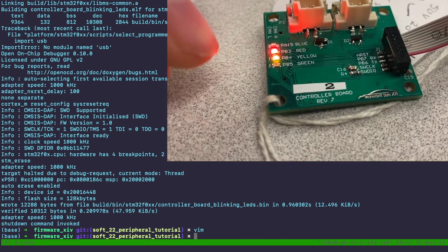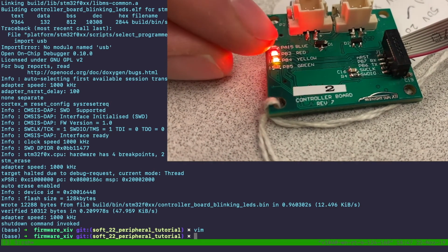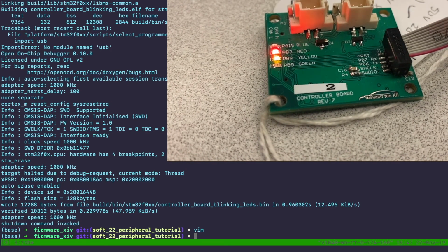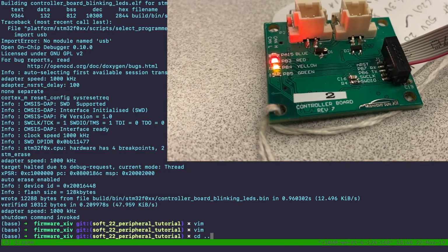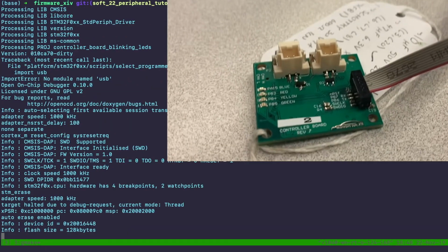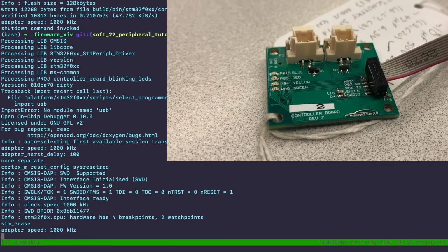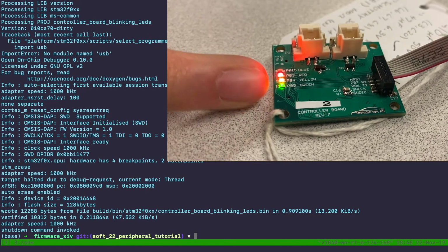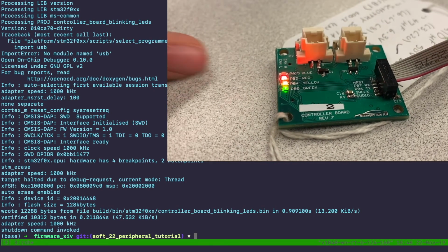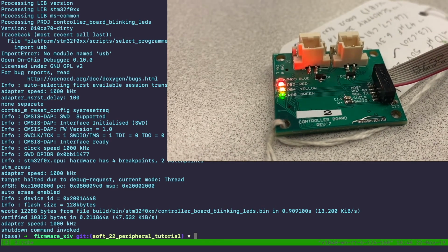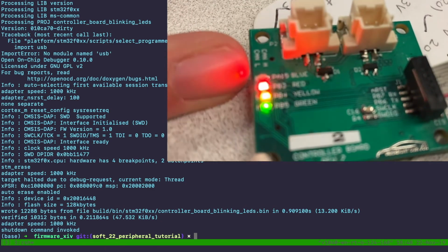As you can see over here, you can see PB5, PB4, PB3, PA15, which are the same addresses that I had in the code. Let's just start running this. Every time I program this, you can see that the board goes off for a second, and then it starts running again. Because in this case it was previously running the same code, the behavior is the same. As you can see, that last LED that's supposed to be the blue LED has come off.